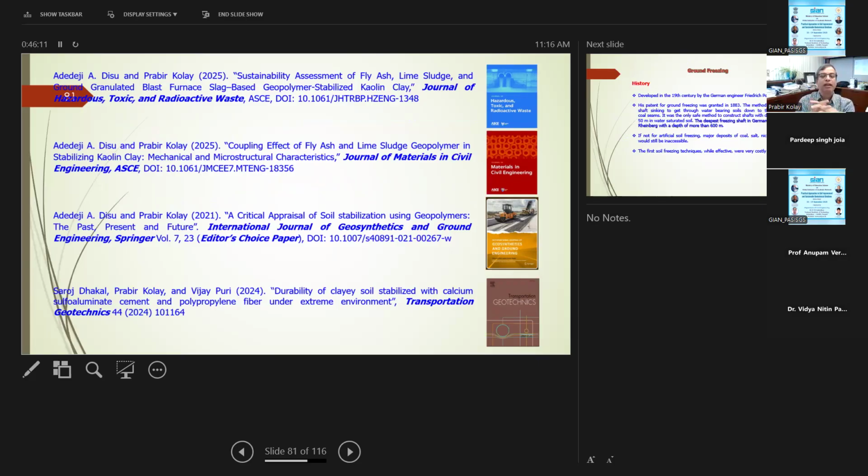So basically, this is the geopolymer. I talked about geopolymer, how when you mix in a dry situation, that is not common. Most of the time you use it in wet form. So what is going to happen? And we discussed ambient temperature, and then also we discussed the curing temperatures. What is going to happen to the strength?